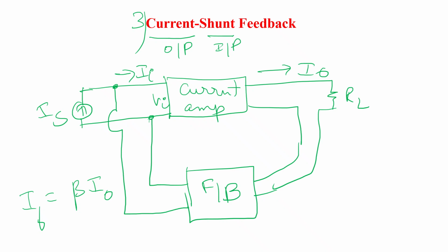to the input. It is a common practice to use this type of feedback to increase the stability, input impedance, and bandwidth. This increases stability by running in parallel some of the output current. This improves linearity, lowers distortion, and gives the amplifier's characteristic more control for reliable performance in a range of scenarios. Yes, this is about current shunt feedback.